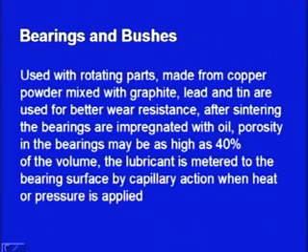So, in secondary manufacturing we have seen that it can be impregnated, or infiltrated, or machined, coining and sizing, impact forging, different types of processes are there, out of which one of the most important processes was infiltration or impregnation. So, here the oil can be impregnated into the porous bearings, which will give them the property of self lubrication.